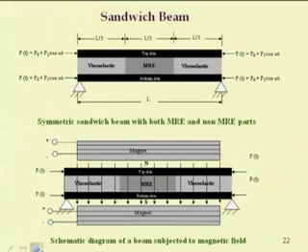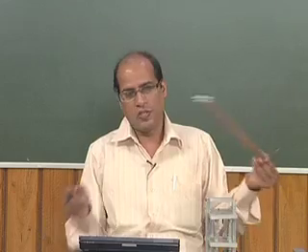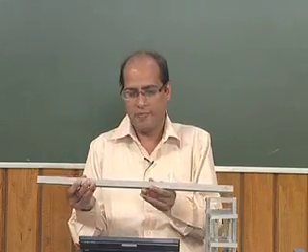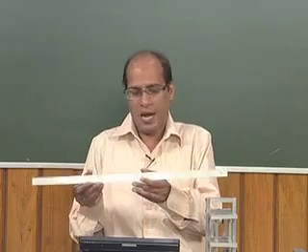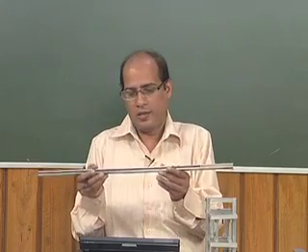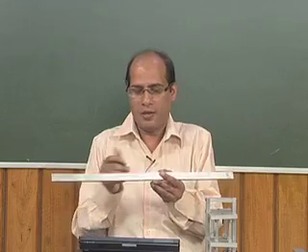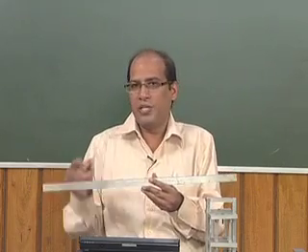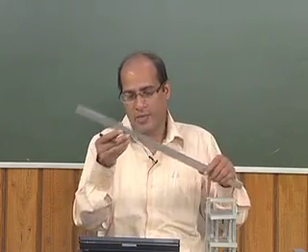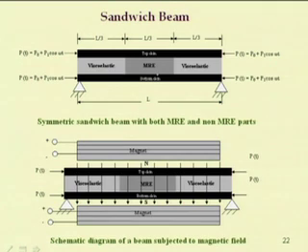So, I have already shown you different types of system. This is a sandwich beam. In case of the sandwich beam, you have a core and you have the skin, and this core you can modify by taking different patches. So, you can add piezoelectric layer also. You may add magnetorheological elastomer core also. In case of this magnetorheological elastomer core, or in short MRE, if you are adding, then you can actively or passively control the vibration of the system.